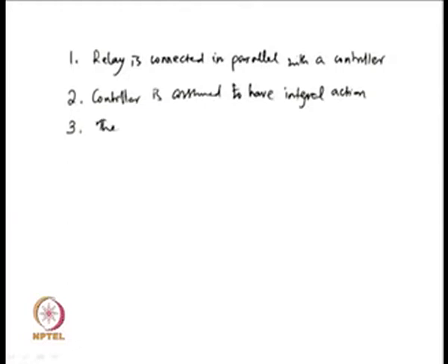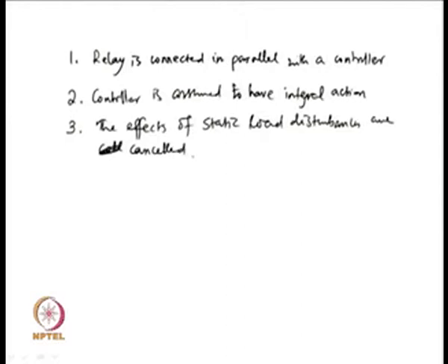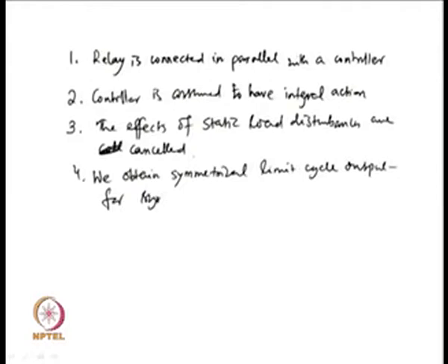Now, what is the benefit you get by that? Then the effects of static load disturbances are cancelled, and we obtain a symmetrical limit cycle output for symmetrical relays.